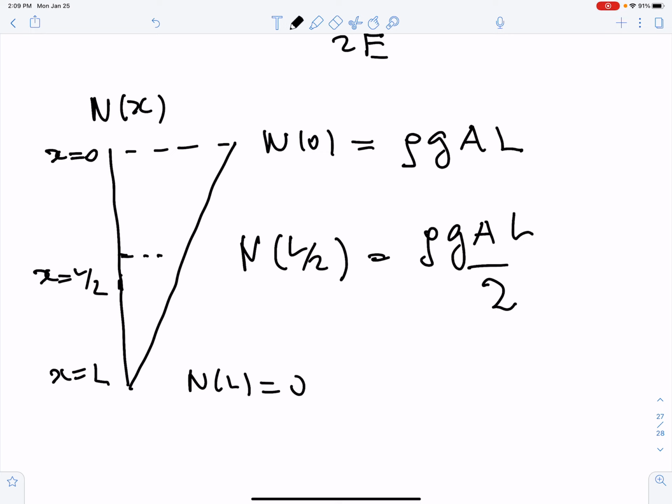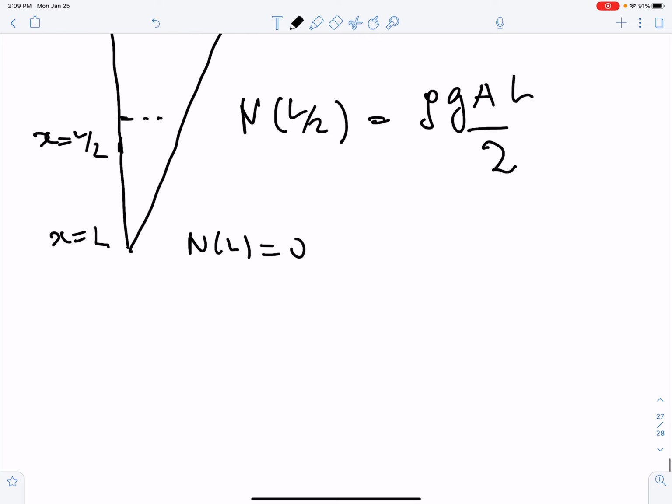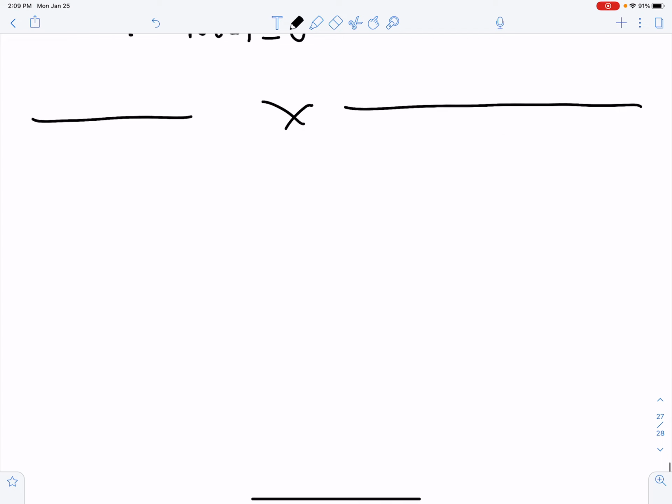And so this problem shows you how these differential equation type approaches give you everything you need to know about the problem. And now that we've set up the problem, set up the differential equation, looked at boundary conditions, and constructed solutions, I think we're at a good point to talk about the concept of a stiffness matrix.